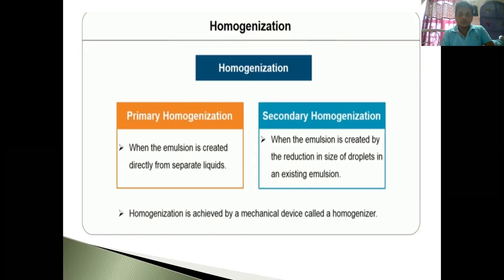Okay, so first of all, you have to know what the homogenizer or the homogenization process is. Basically, the name says homogenizer means uniform size. According to the United States, homogenized milk is milk which has been treated in such a manner as to ensure breakup of the fat globules to such an extent that after 48 hours of storage no visible cream separation occurs on the milk, and the fat percentage in the top 100 ml of milk. Basically, in milk the fat globule is the largest size.